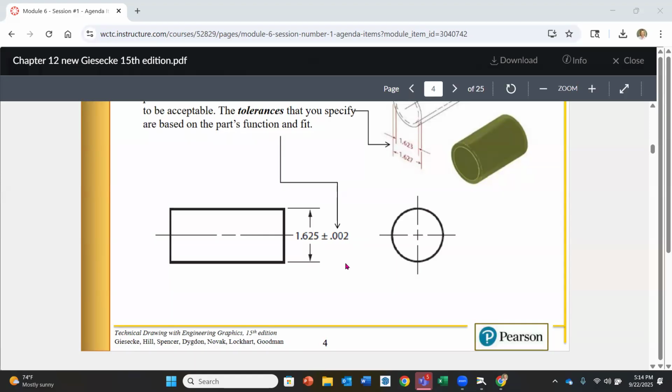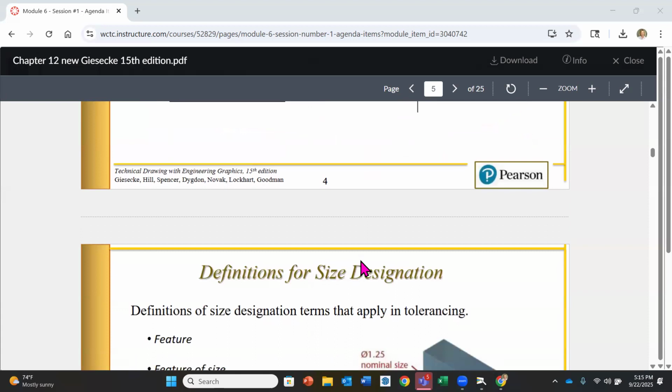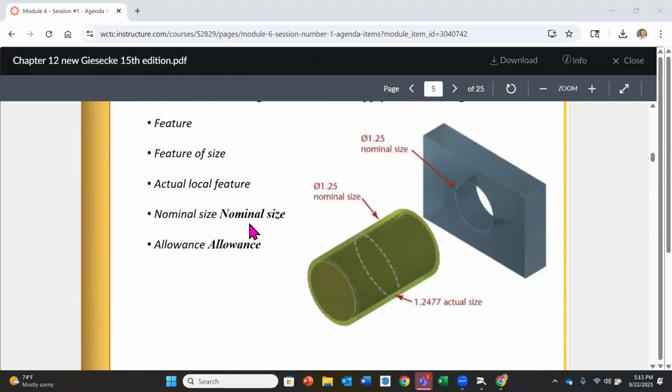As designers, when we know which units of measure we are working in, whether it's English or metric, we want to make sure that we are using nominal sizes that are consistent with that unit of measure. For instance, if we have a hole and we know we're going to be drilling it, we want to make sure that we don't have an obscure decimal value. We want to tie it to the size of the drills that would potentially be used for making that particular feature.